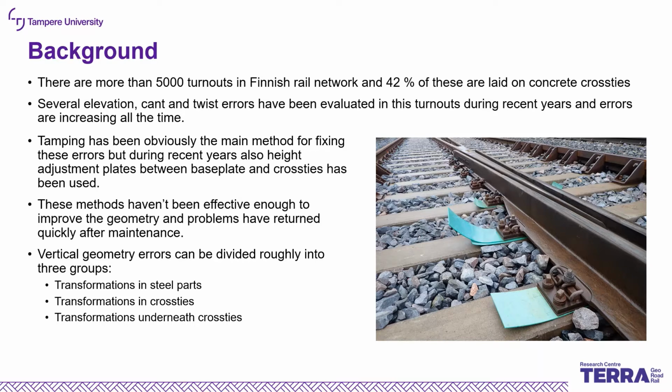So we really want to understand why there are elevation, cant and twist errors, and what the reason for these is. They have just been tamping and using the adjustment plates, but there hasn't been real understanding of what is happening, why we have to use so much tamping and why we have to use these adjustment plates. So this project